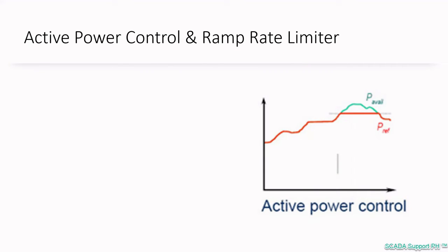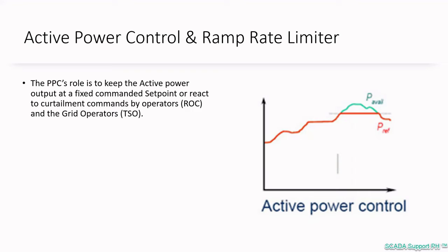When we talk about on-demand active power control, it's usually performed in the range of plant nominal power or within contractual limits. The output active power of the solar PV power plant is constrained to a predetermined power or megawatt limit at the point of interconnect using an absolute production constraint.